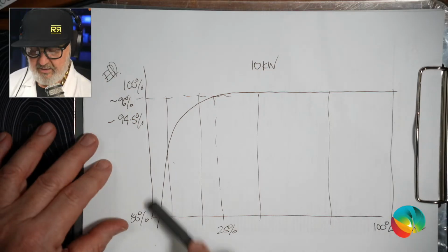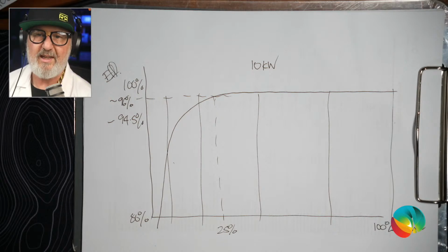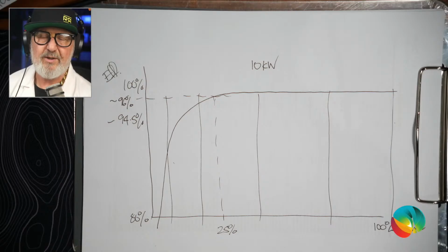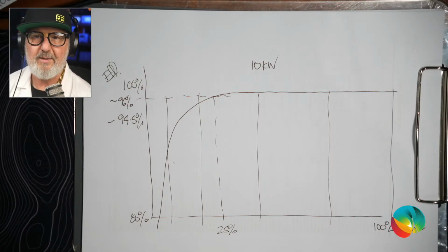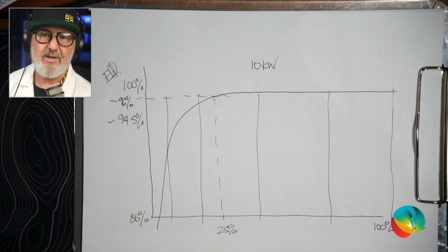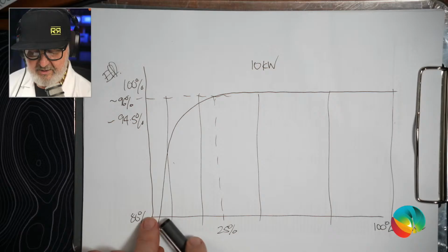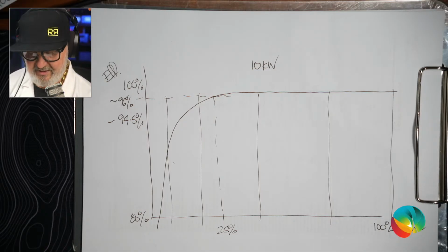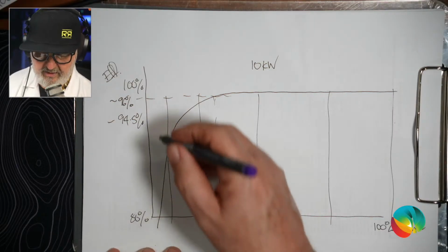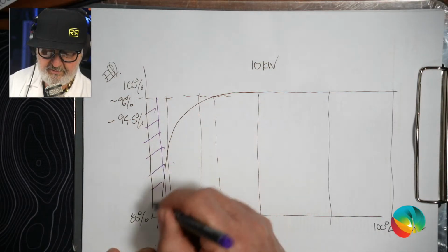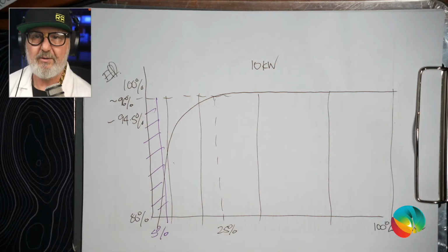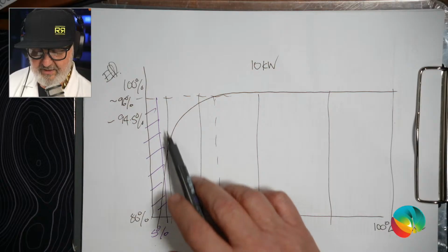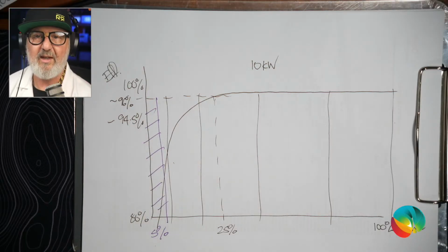Just one other note too. Now I've drawn this curve here, I just remembered last week, I was talking to you about standalone power system design and how battery inverters with basically toroidal transformers inside them are generally less efficient than string inverters, which are transformer-less. It's partly because in this part of the graph, they've got quite a lot of self-consumption. It's often due to eddy currents in the transformer and thermal losses. So a large toroidal transformer might be gobbling up the first 5% of your production all the time. And so you're losing the first 5%. So that's why their efficiency is not so great at low power levels.